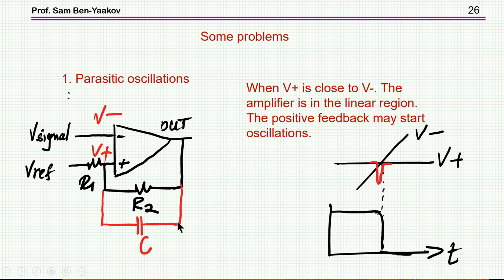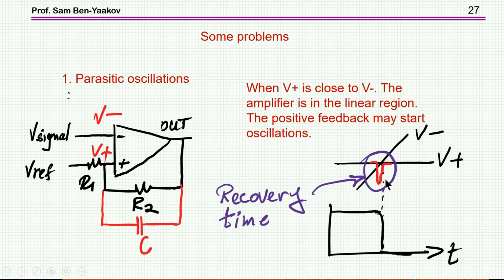Now what happens with the capacitor is that it accelerates, speeding up the change and very quickly moving to the other state and locking the amplifier to the other state. This would be one purpose of this capacitor, and once it is changing, it is actually changing the voltage here, so it's increasing the difference between the signal and, say, the reference. Unfortunately, it takes some time for this to recover.